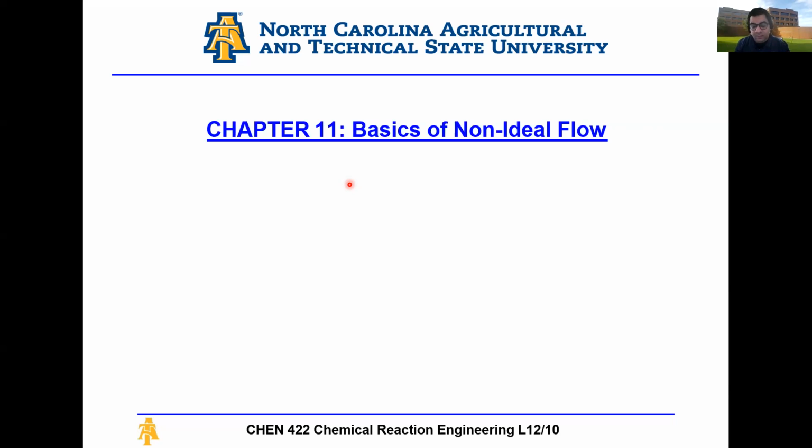And the validity of these types of assumptions stops as you move throughout your design process. So at a very high level design, let's say you're designing a plant, you can use these reactors to give you a good estimate, or an initial estimate, of the overall volume of the reactor, which you can use for sizing. And Aspen Plus will use these types of ideal assumptions for designing reactors as well.